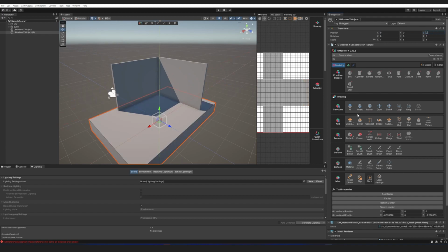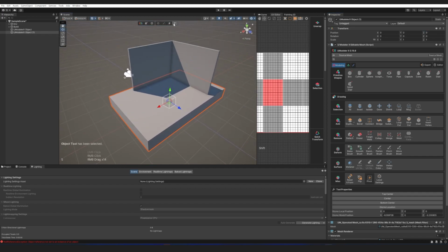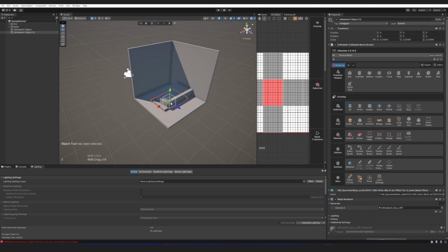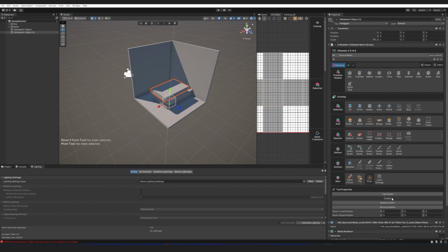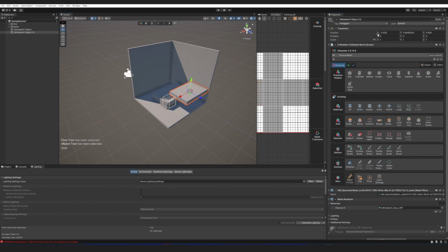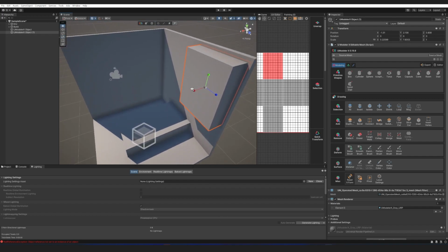Even after creating a box object, you can adjust its position and size. To select an object, ensure the Object Selection button at the top of the screen is active. Change the object's pivot value to center. When the pivot value is set to center, the object's coordinates shift to its center. In this state, modify the position and size of the box to create a shelf attached to the wall.